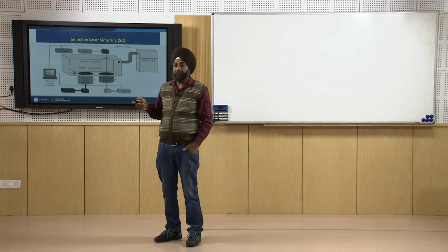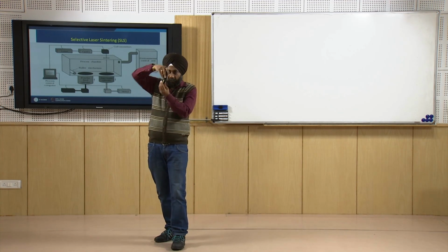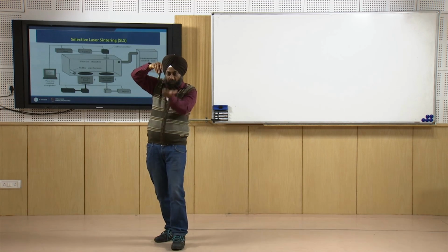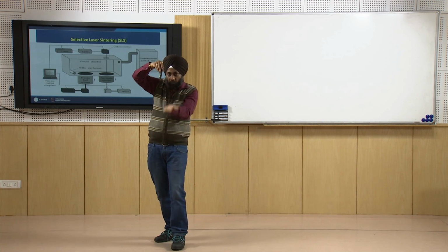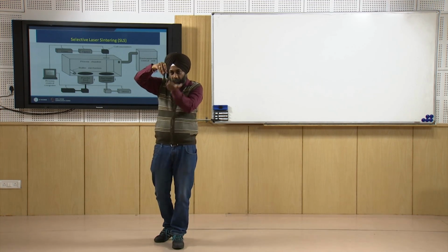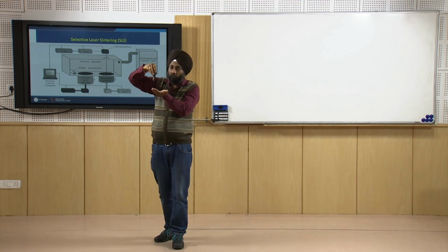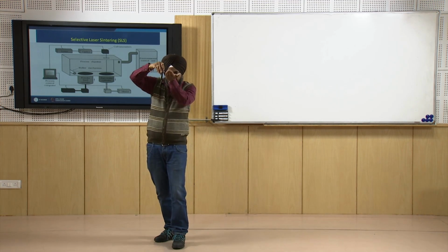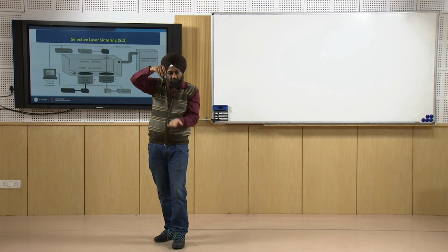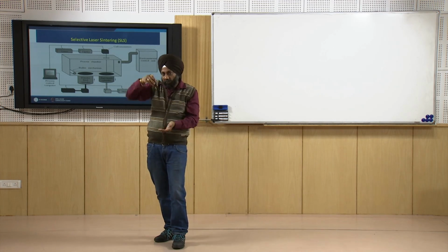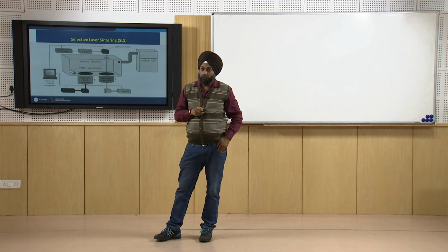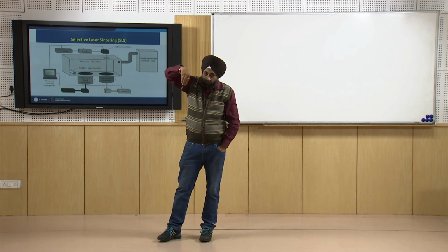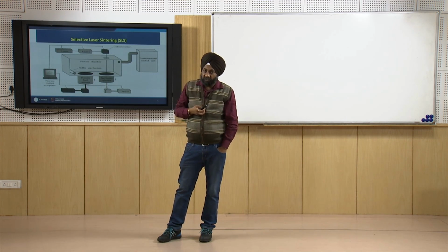Similarly, in a rapid prototyping system also we have to ensure the gun can move in x and y direction. But in order to generate the third dimension, either we need to move the gun up and down or we need to move the table up and down, and in many cases we will see the table will move. As in case of stereolithography, the platform was moving down incrementally layer by layer. Similarly, in selective laser sintering also the movement to the table has to be provided to ensure the third dimension to the platform, because the 2 dimensions can be covered by the movement of the laser gun.